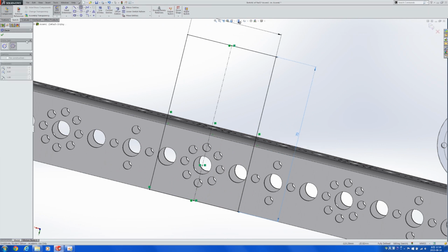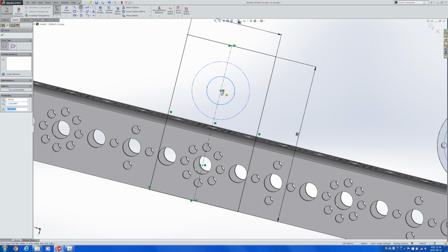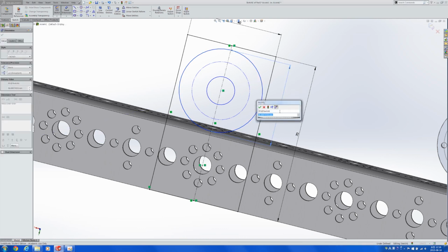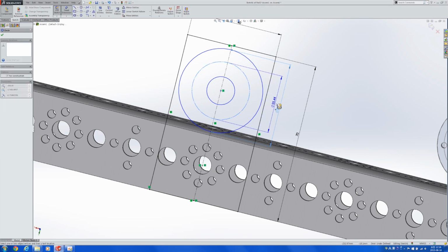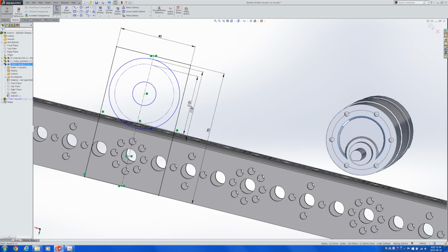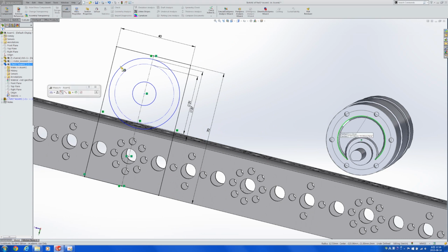Then here, what we can do is make a circle that is for construction. Actually, around 3 circles. This circle will be for construction. The smaller inside one will be just a circle, and another one will be just another circle. This will be 37 millimeters. This will be 31. And the inside one will be, I don't remember what this one was, 12.50, so 25 millimeters.